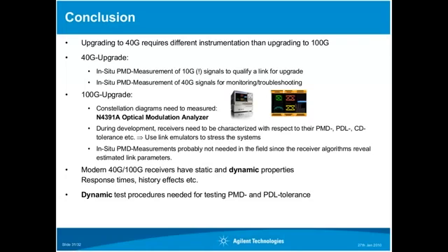And the whole thing is distributed like a Maxwellian distribution. So most of the time you will see the 10 picoseconds, but there are a few occasions where you see 30 picoseconds. And well, as a rule of thumb, people say that in practical applications you will see up to three times the PMD coefficient. So 40 picoseconds you probably will not see at all. 30 picoseconds you might see, but not very frequently.